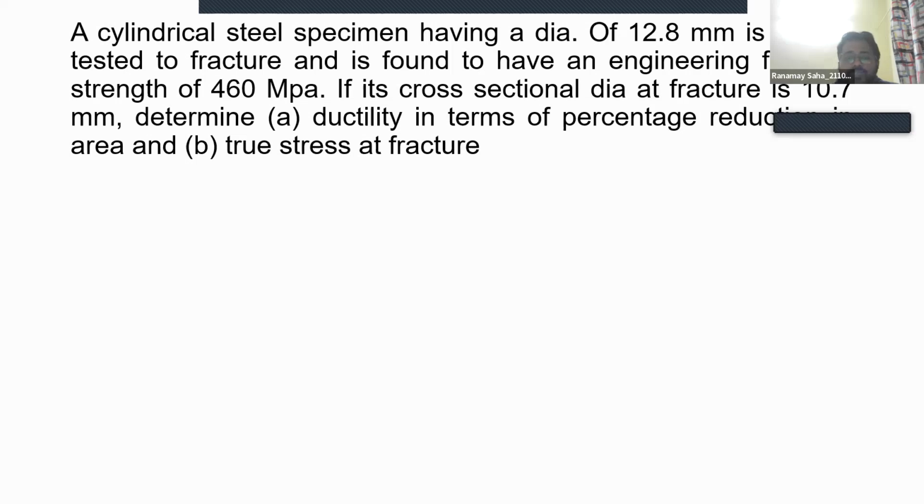This question says there is a fracture strength of 460 megapascals, and if the cross-sectional diameter at fracture is 10.7 mm, you have to determine the ductility in terms of percentage reduction in area and the true stress at fracture. You guys try. I will give you some time, and then I will share the solution.